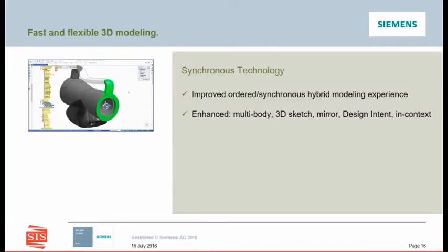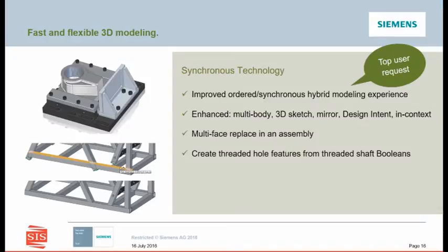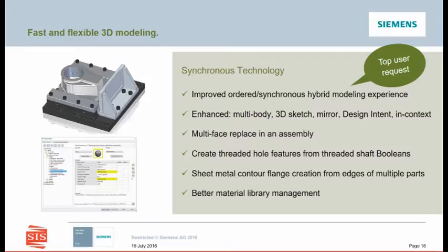So synchronous technology in Solid Edge continues to improve, providing even more speed and flexibility. We saw the hybrid experience of combining history-based with synchronous-based modeling. But that isn't all inside synchronous technology that's been improved. Multi-face replacement, even within assemblies. Creation of hole features and cutouts from threaded shafts and Boolean solids. And sheet metal contour flange creation from edges of multiple parts from the assembly.